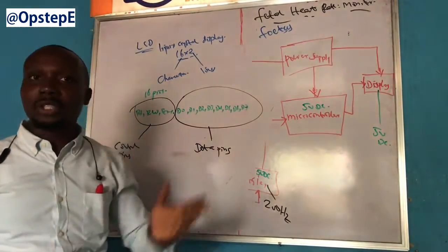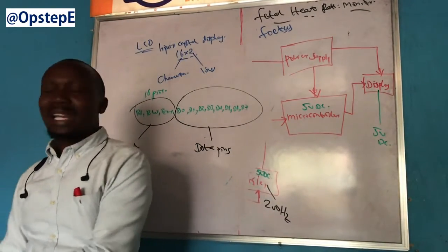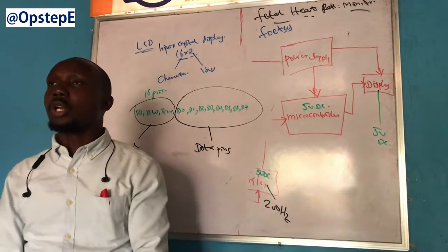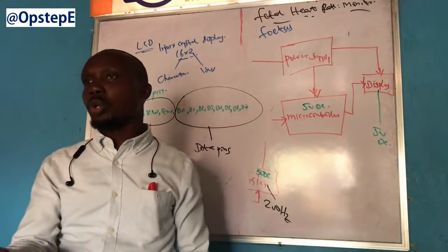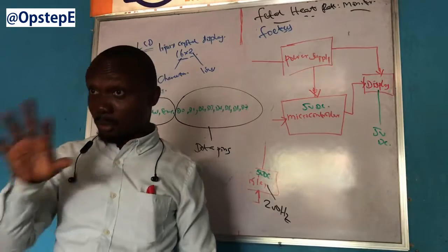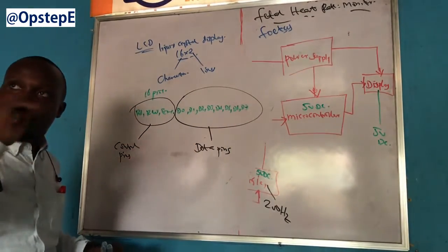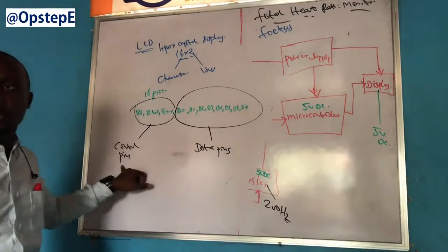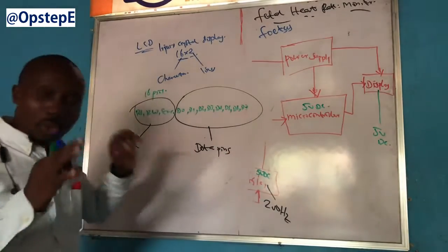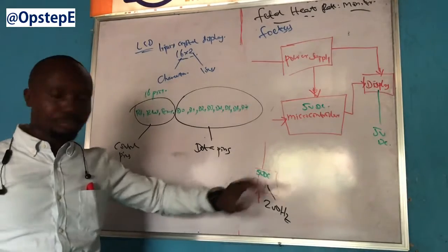Before you send characters to the display line, you need to tell the LCD, please move your cursor to this point. Clear what was there before. I want to write something new. Okay, go from line 1 to line 2. Or don't put that thing on line 2, put it on line 1. Or blink before you display. Are you with me? All those control commands are sent through the control pins, while the information that needs to be displayed is sent through the data pins.